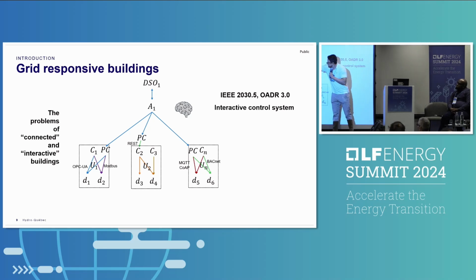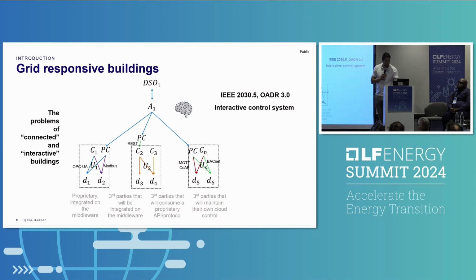So they use a standard communication bus up to the protocol conversion system, and then the protocol conversion system converts to MQTT, converts to Zigbee, converts to REST, to whatever protocol is being used on the edge. So that somewhat solves the problem of the protocol, but it will still be a messy system.